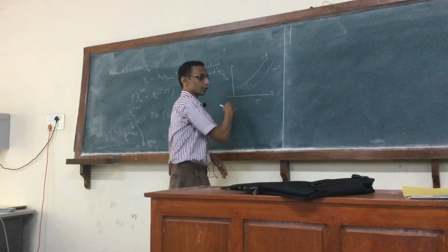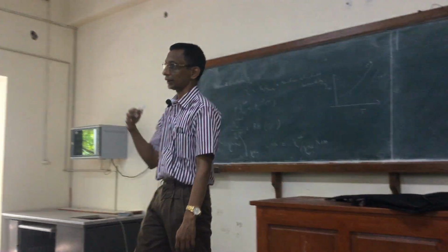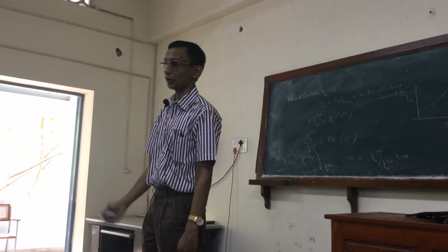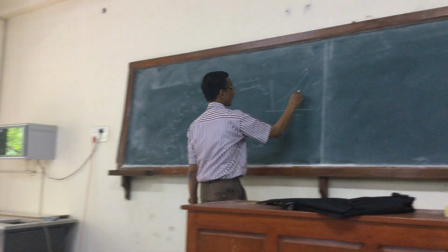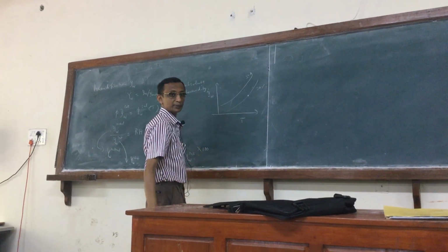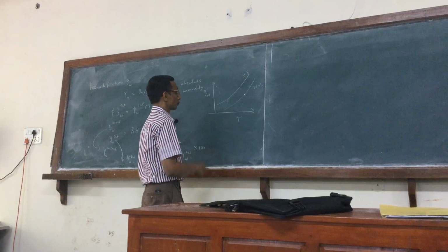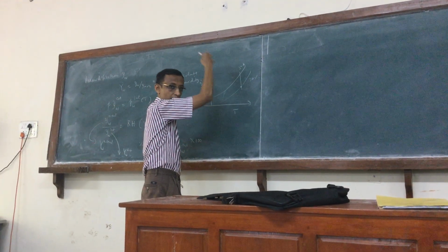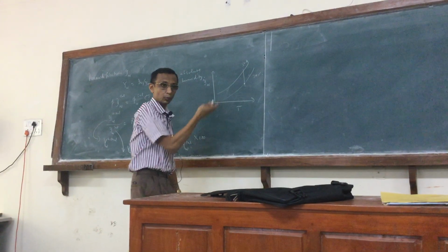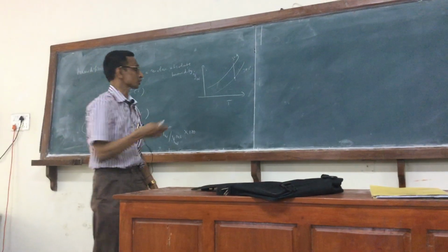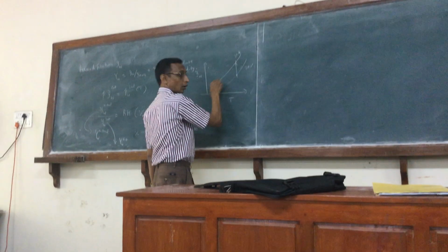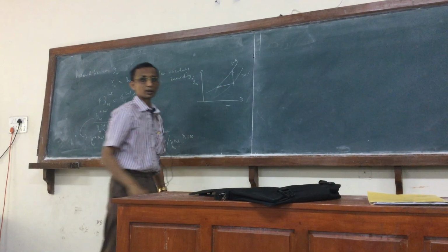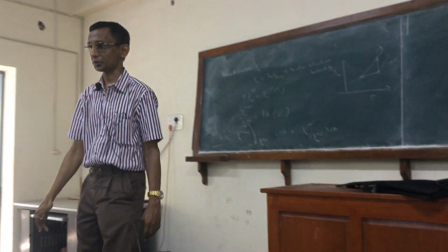You can look at the concept of dew temperature, either in terms of the mole fraction or the mole ratio. So if I have a mixture which is at 70% saturation, to bring it to saturation, I can either follow this route, keep it in contact with water for a longer time so that more water evaporates and it reaches saturation. Or the concept of dew point or dew temperature will be cooling the mixture to bring it to saturation.